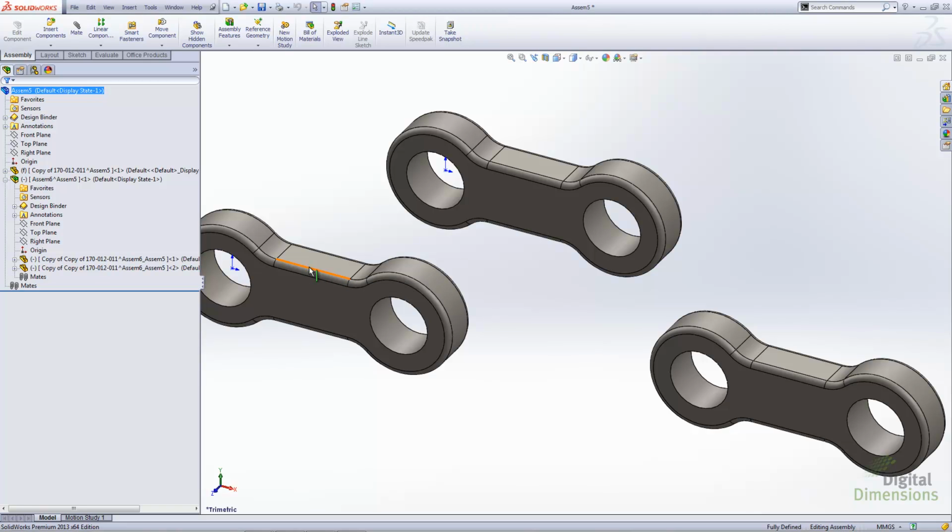The reason for this is that the new copy has no link to the original. Just by definition of virtual components, these are components that live and are embedded within the parent assembly file. Since we've made that change, we can't actually do a move in the traditional sense. It's going to be a copy.